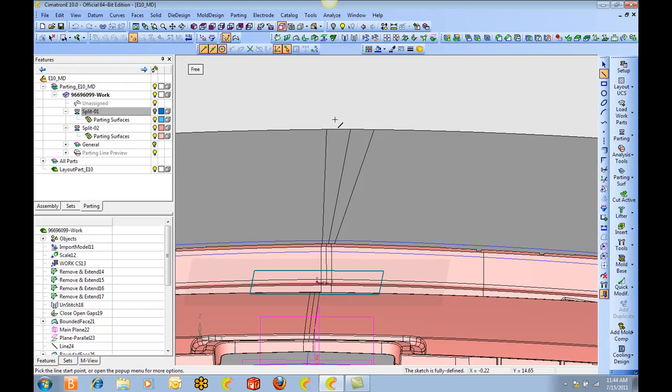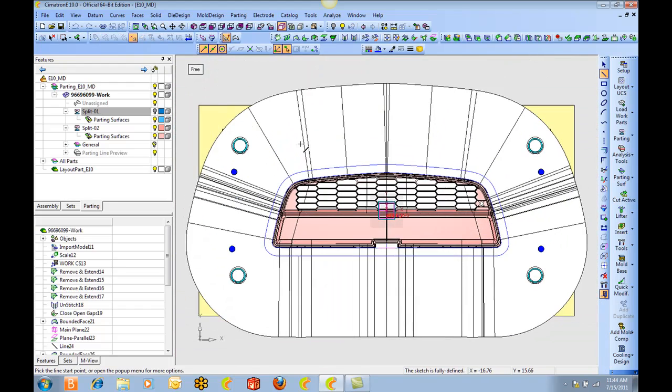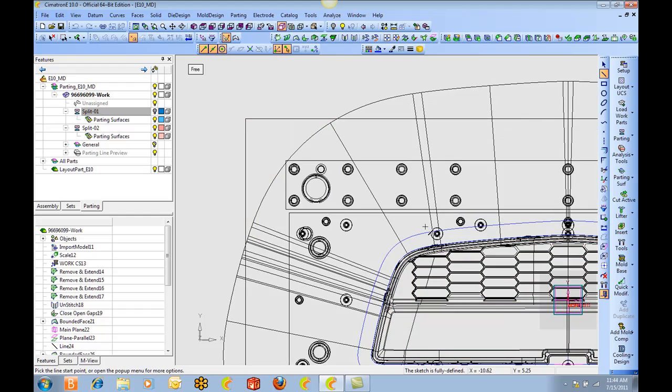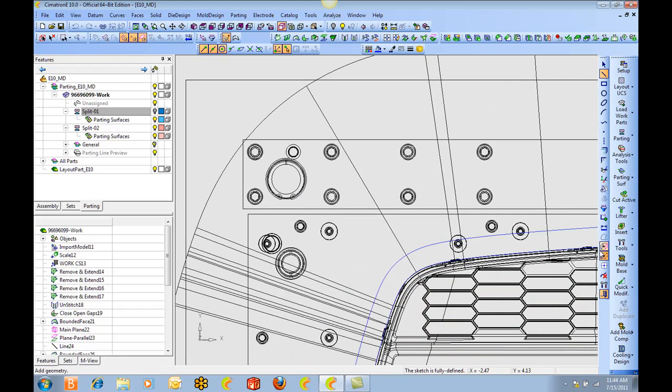And this is where we'll sketch the lock. I'm going to the top view, I'm going to wireframe. I'm going to add reference to this corner. I go to the box tool, you sketch a size for the lock, dimension it.